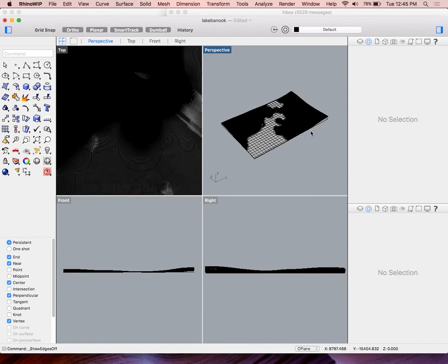So this model that we are doing is 2 laser beds put together. So that is essentially too big to fit on the laser cutter. So when you take it into 123D Make, can you specify a boundary in there that will cut it in half automatically? If the model that you're bringing in is 32 by 36, it knows the bed size is 32 by 18, so it's going to choose the most efficient way to do it.